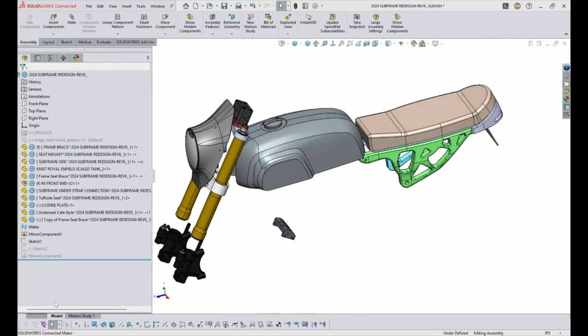So to designate a virtual component, you'll see it in your feature tree with brackets, a caret, and then the name of the file that you're working in. Virtual components are only for assemblies, so it's always going to be the name of the assembly that you see after the caret. My feature tree has the maker logo in here, so a commercial version would not have this, so don't let this worry you. When we scroll down the tree, I have a lot of virtual components, but I have this tank here that is a regular file. It's got an external link.